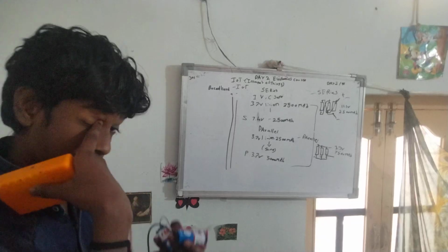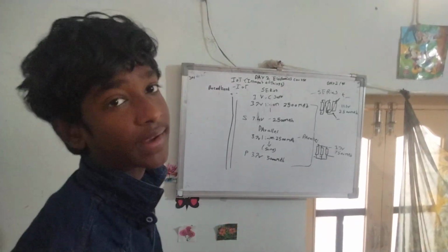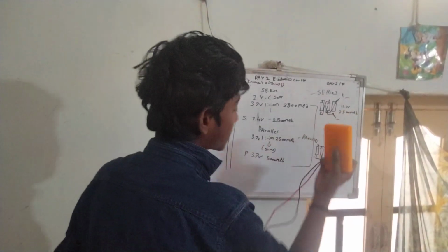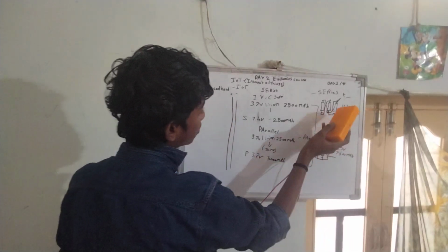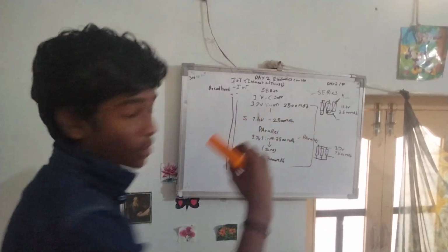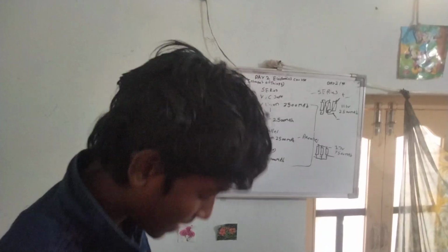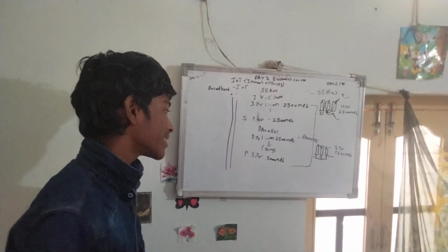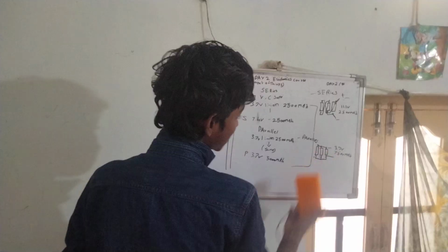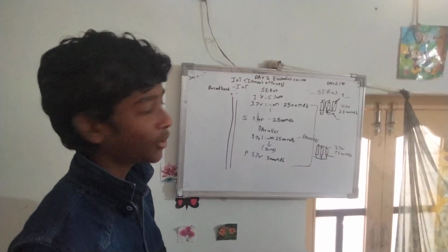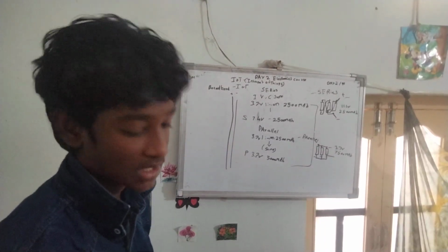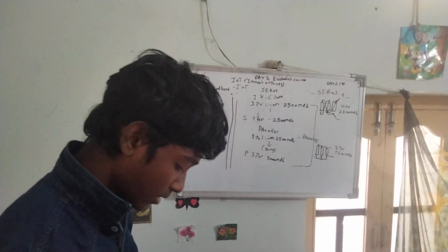So yeah, I don't have any spare batteries to show you the connection, but these are the connections. Series connection is nothing but positive to negative, negative to the other positive of another battery. Connect the opposite terminals of each battery. Parallel connection is simple: connect all the positives and all the negatives together to get two ends. You will get the increase in capacity.